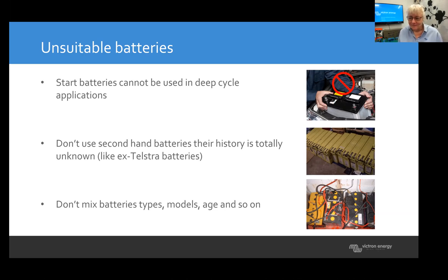The performance of a system goes by how well the batteries perform. If the batteries can't deliver the power, the inverter or the inverter charger can't convert it and make AC out of it. So if the batteries are not good, the inverter is no good. They're that closely related. So perceived inverter problems are quite often caused by some issue with the batteries or with the battery cabling. That's why we have a book on wiring, for instance.